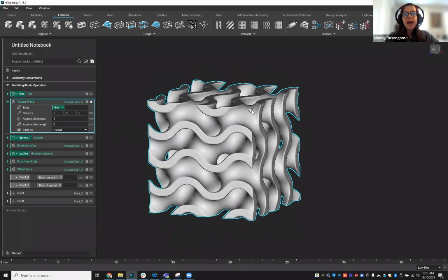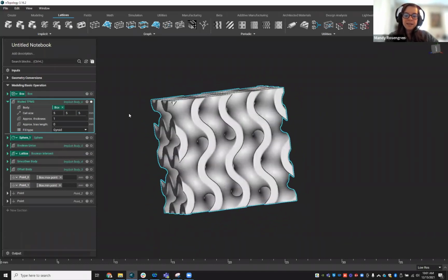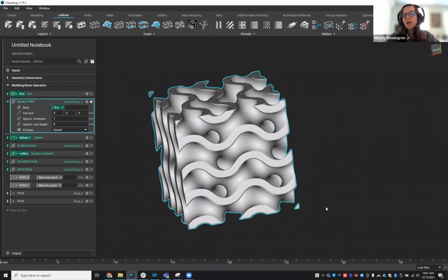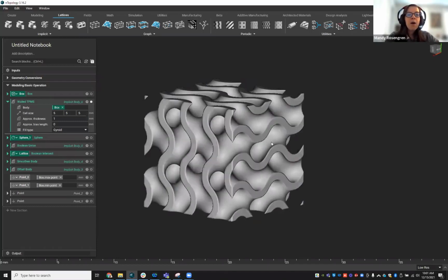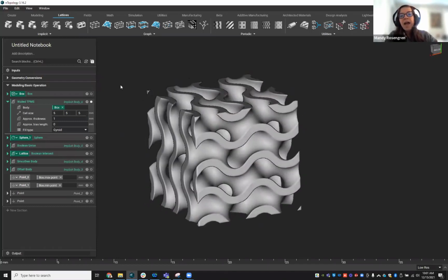So we can see I have this little floating piece here, and if I wanted to print that, I wouldn't want those two areas. This could also happen if you have another type of body with floating areas in it. Maybe you're importing something, and when you convert it to an implicit body, this occurs. But this is just my one example. The best way to go about this, I would suggest, is to use our split mesh option.